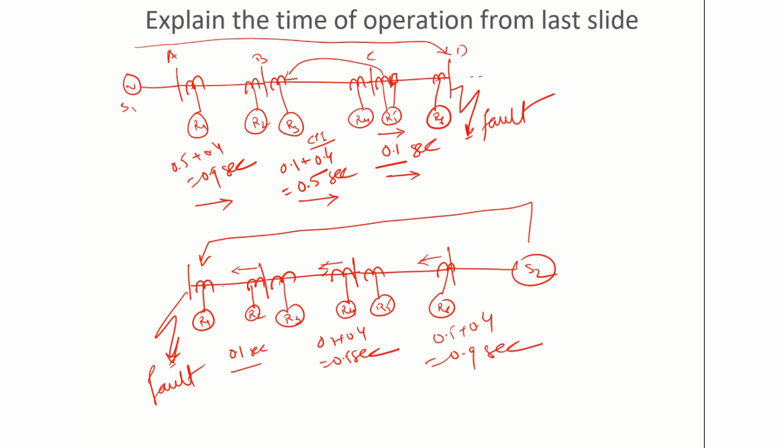So now, if we just club both, that is with source 1 and with source 2. If you want to club them now, then what happens, this relay 0.9 second, R2 it will be 0.1 second with direction this, R4 0.5 second from here with this direction, R6 0.9.